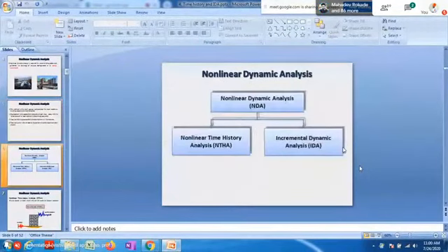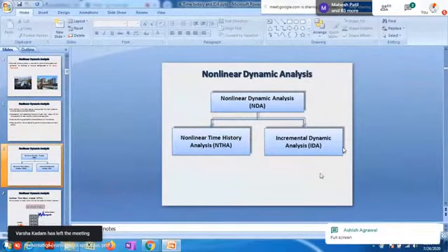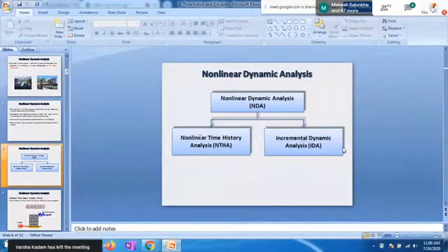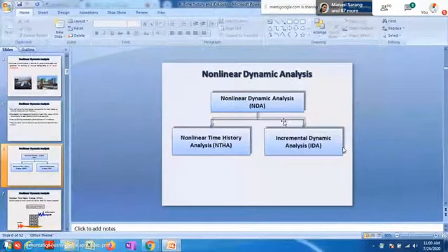So non-linear time history analysis is the regular, conventional one. And going in depth, if we continue, it is incremental dynamic analysis, IDA. What output do we get from a ground motion? We get the response of the structure to that ground motion. Response in the sense of acceleration, velocity, displacement in the structure. What are the nodal displacements? Nodal displacement, drift, displacements, all for a particular ground motion we will get.